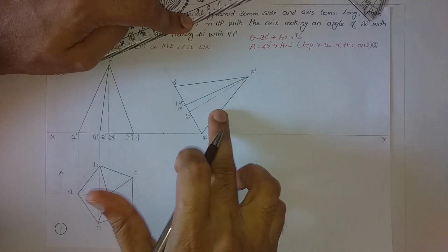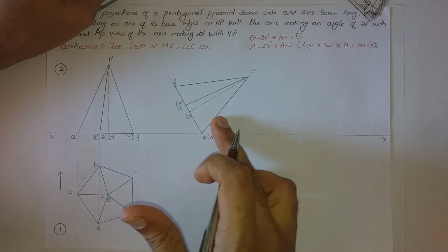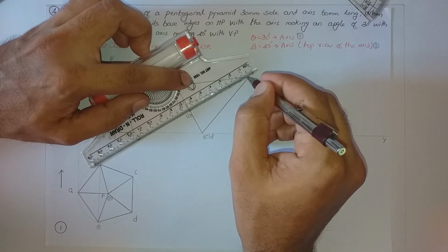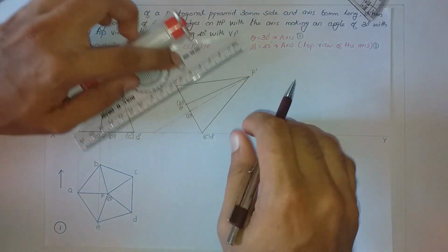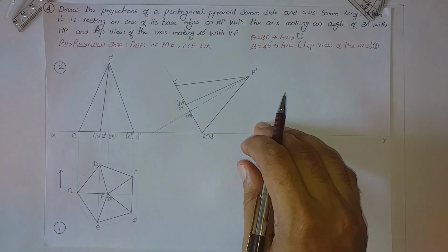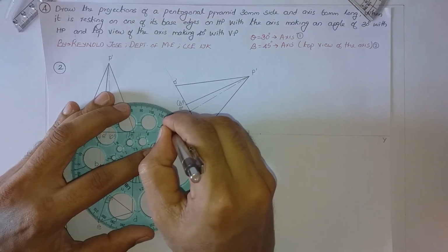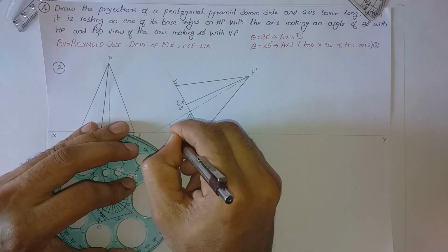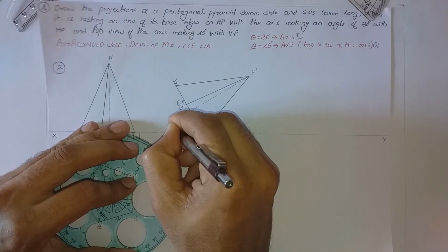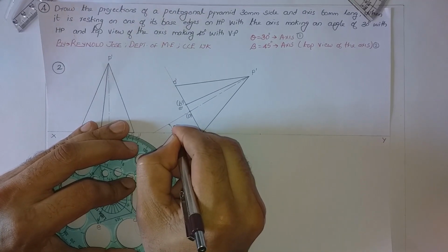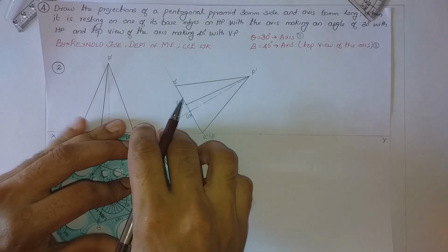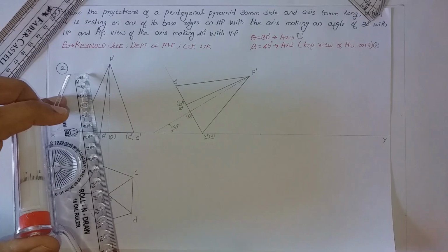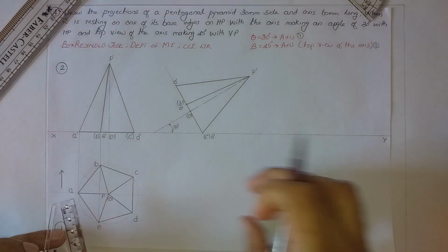Exactly these two diagrams are the same in their dimensions, the only difference is in the inclination. Here the axis will be having an inclination of 30 degree with respect to HP. So this angle is 30 degree. Now we shall draw diagram number 4. It is by extending projectors from this front view and previous top view.